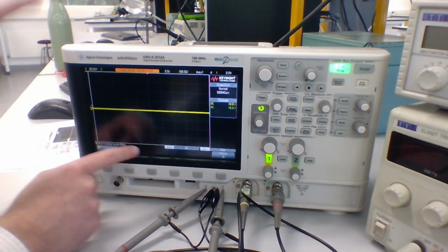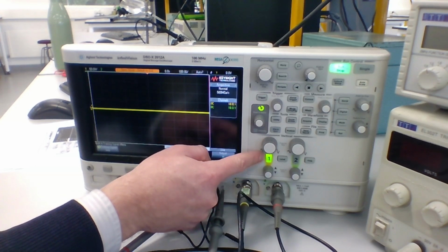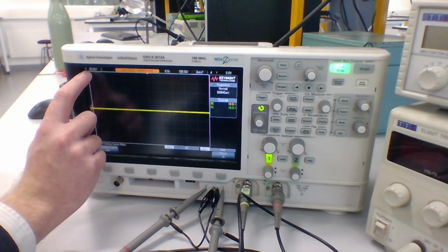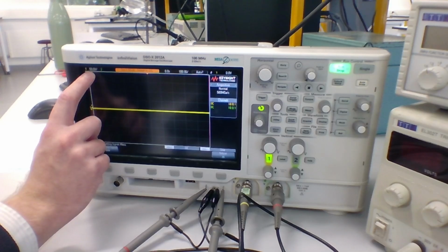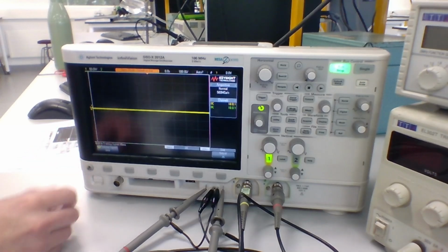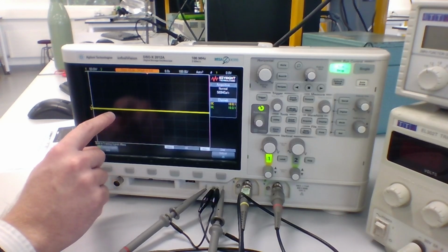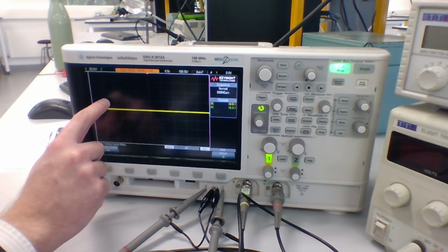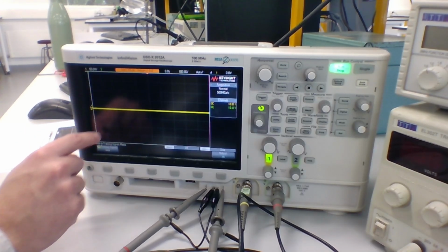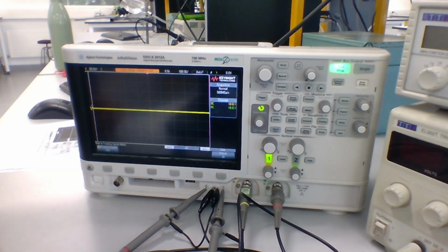To change the vertical scaling here, we use the large vertical dial here above channel 1. We turn that to change the scale. The scale is represented or stated at the top here as well. Currently it says 50 volts slash. We read that as 50 volts per div. On the screen you can see there are all these grid lines. At the moment this is set up with, vertically speaking, 50 volts between each grid line going up or down the screen. And that's quite a large scale. That's probably larger than what we're seeing.